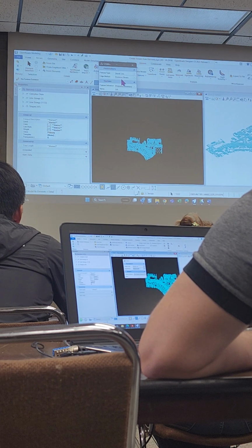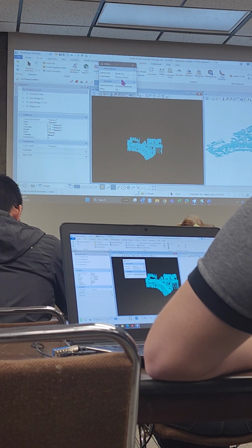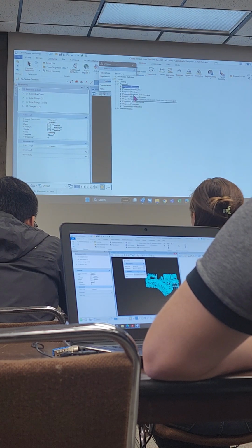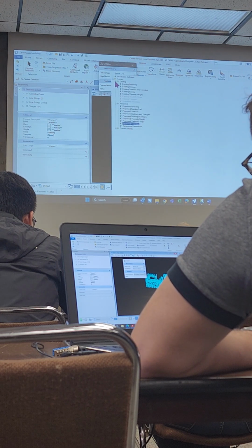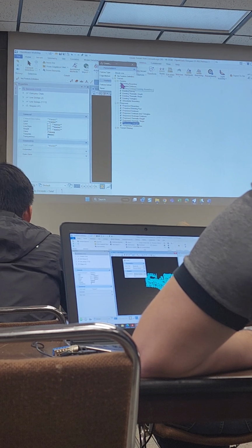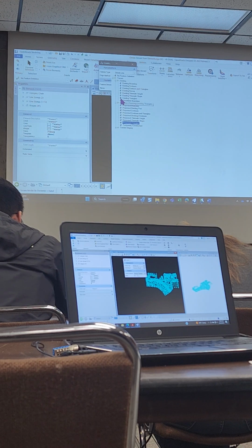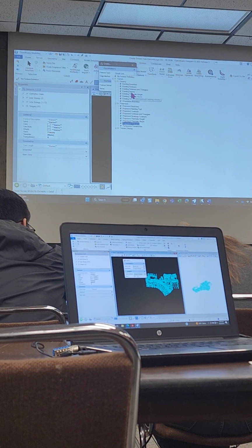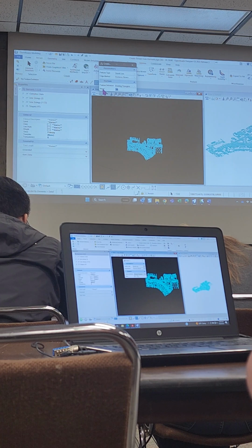So that's kind of like the magic button that will go in and programmatically look for small slivers and triangles on the edge and remove those. And then for the feature definition, we'll choose existing triangles. So what you'll also notice is you've got these gray palettes. As you use a feature definition, it's going to colorize, and that lets you know it's been copied into the file. So do existing triangles. And I'm going to call this existing for the name.